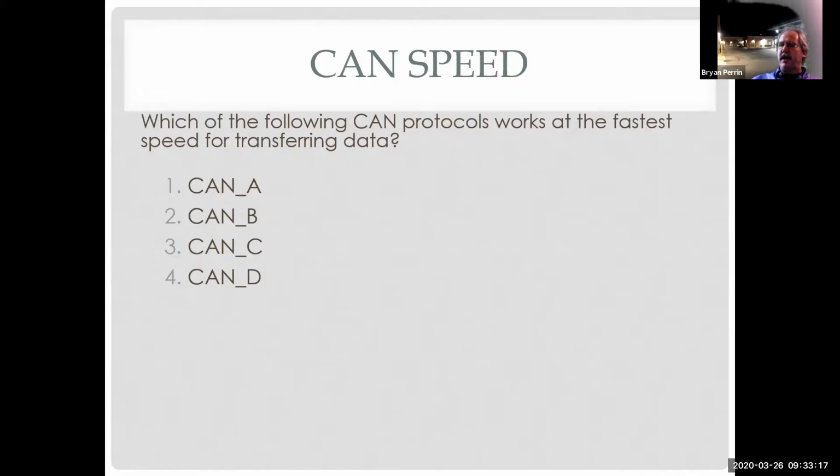So I mentioned GM uses a Class C CAN or Type C CAN network for its OBD2, where it hits the main modules, you know, airbag and so on. Then it has a completely different network on pin 1 of the DLC that talks to all of its supplemental stuff. And if I'm using a generic scan tool, or a scan tool that only goes into OBD2, it's not going to talk to any of those other systems. So sometimes it's an addressing thing, and sometimes it's an issue of whether it's on the correct network.